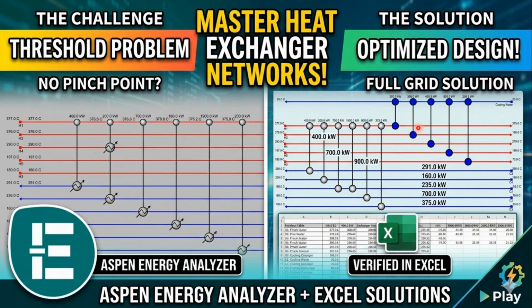In standard pinch analysis, you need both hot and cold utilities, but in a threshold problem, you only need one. It sounds easier, but it completely changes how you match your streams. Today, we are going to design a heat exchanger network for a threshold problem from scratch. And by the end of this video, you won't just understand it, you will be able to design your own network confidently.